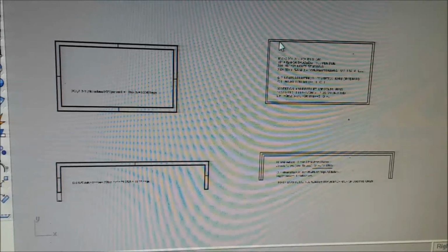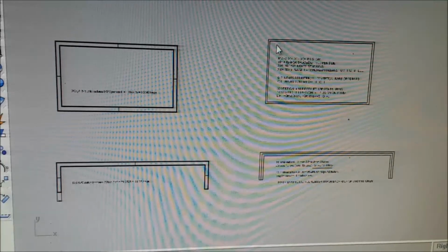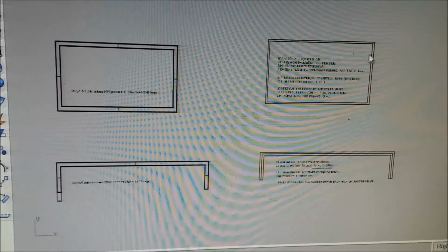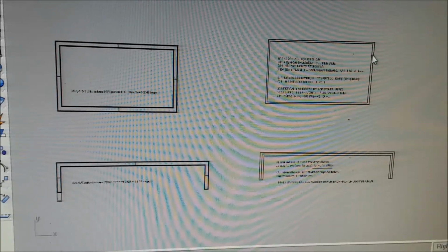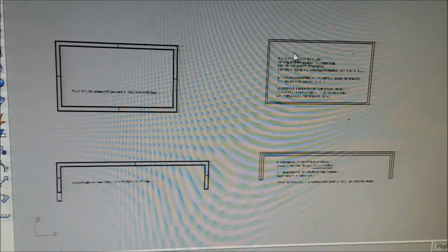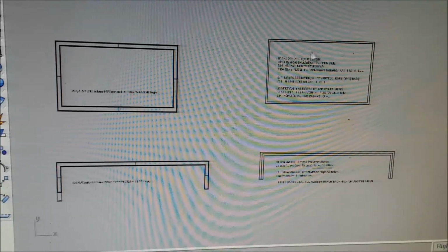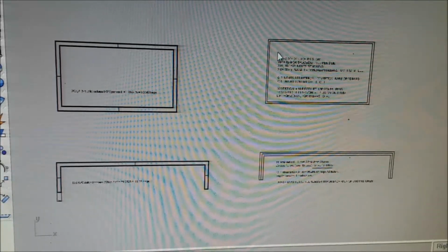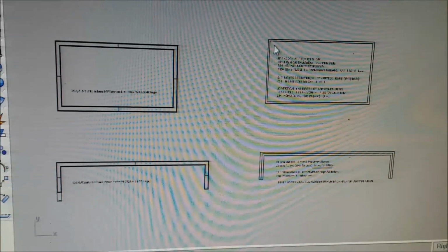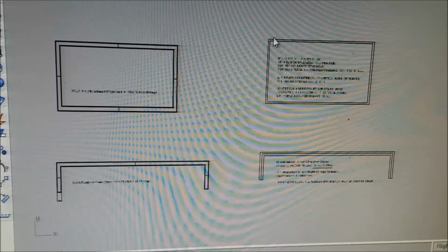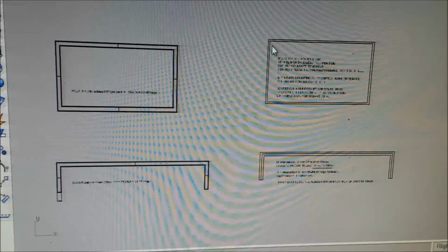So if you add up the actual bars consumed, every other block hole, and every 3rd horizontal row gets a bar end to end, you haven't got as much grid coverage in the wall as you do with the poured concrete. But where we pick up is we don't have to have the bars in the columns or in a top beam.